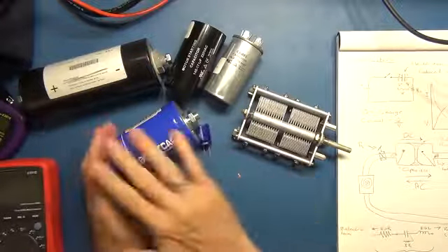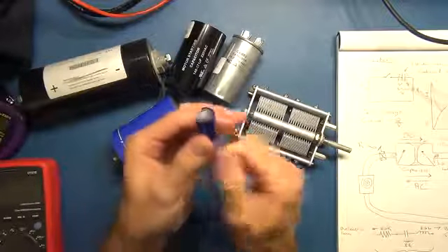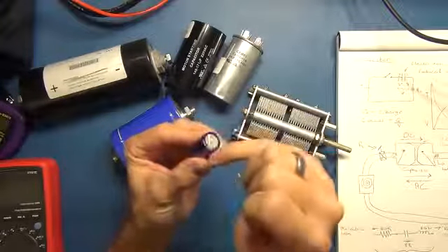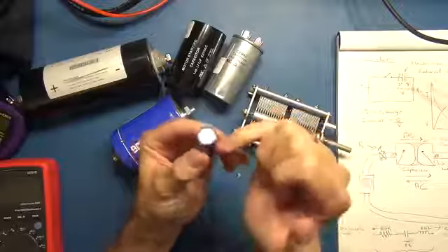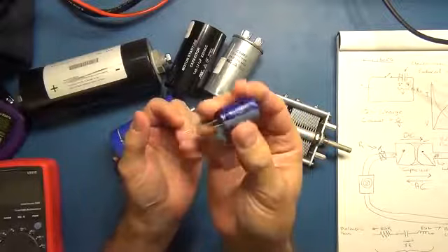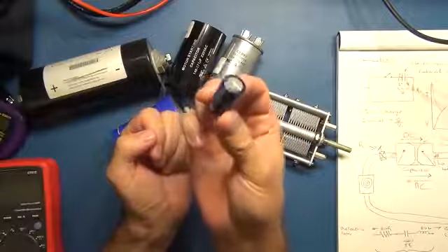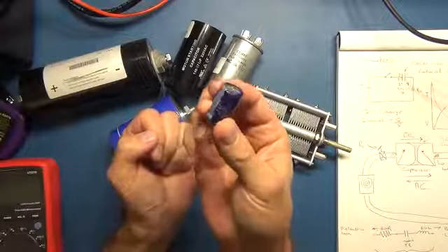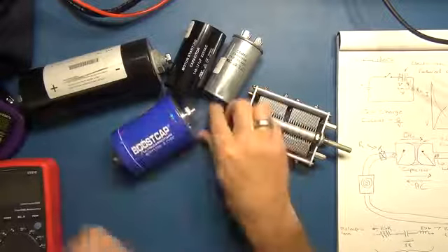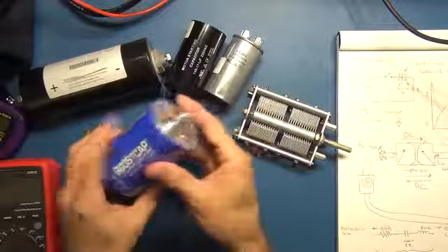Now, as I said, you get capacitors of all types. This is an electrolytic, and inside the electrolytic you're going to have paper that's coiled up as a dielectric to separate the plates, and potentially a wax or some fluid in there, and that we'll talk about as potentially an issue. In power supplies and electronics particularly, capacitors can be the downfall, because they are one of the key pieces to look at in terms of fault finding, because they can fail relatively easily. Then we will talk about the supercapacitors and the role they play in the future.